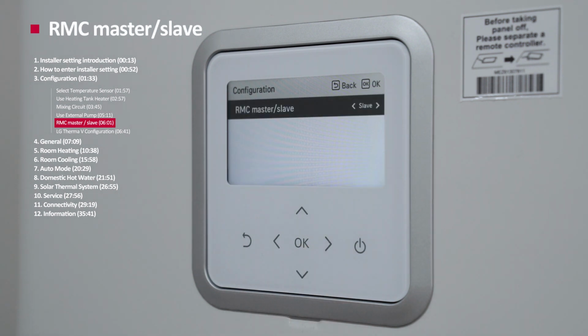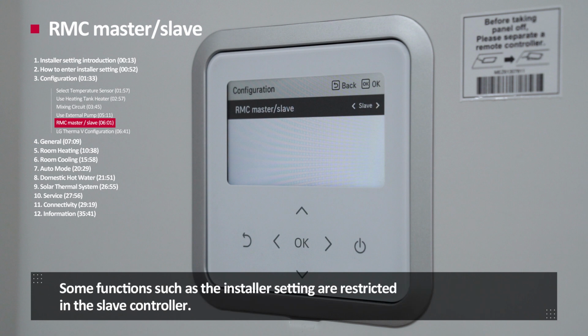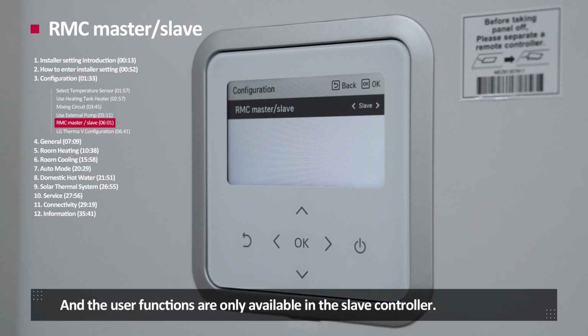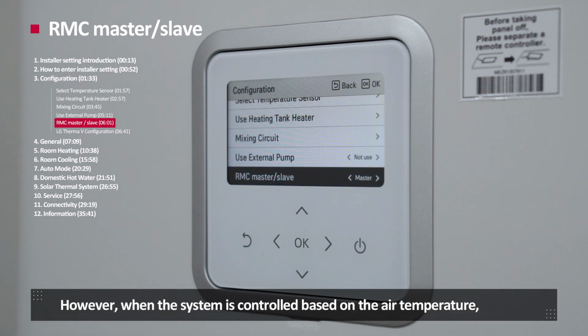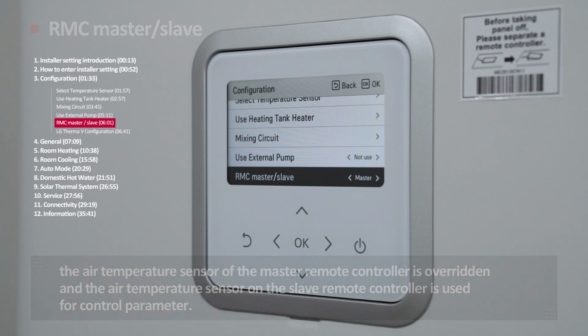RMC Master Slave. The RMC Master Slave function allows you to select which remote controllers to set as master and slave, where 2 remote controllers are used for 1 unit. Some functions, such as installer setting, are restricted in the slave controller, and the user functions are only available in the slave controller. However, when the system is controlled based on the air temperature, the air temperature sensor of the master remote controller is overridden, and the air temperature sensor on the slave remote controller is used for control parameter.